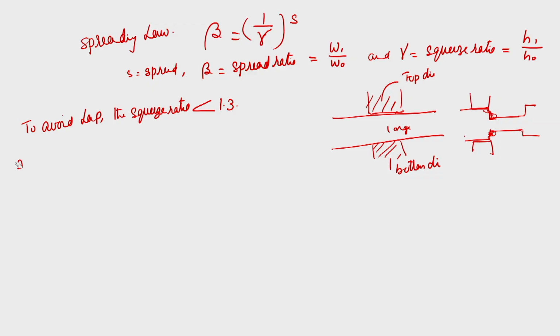So when you want to do that, the main purpose of this is mainly to break the structure, especially dendritic structure, coring, segregation, all those things you have to change. So the deformation strain should penetrate up to the center. If the strain is less than a certain amount, the whole purpose will not be met. So for that case, the bite ratio for the deformation to ensure that